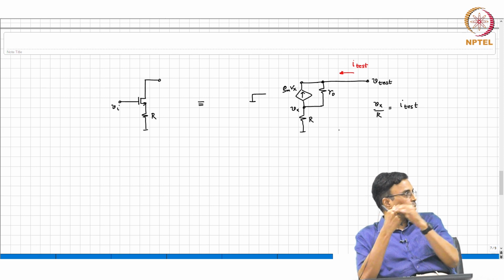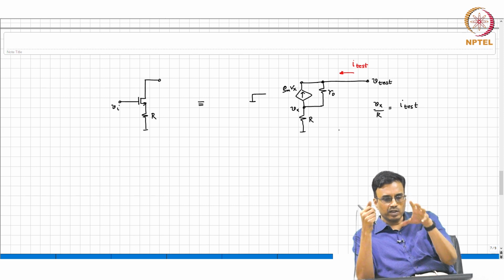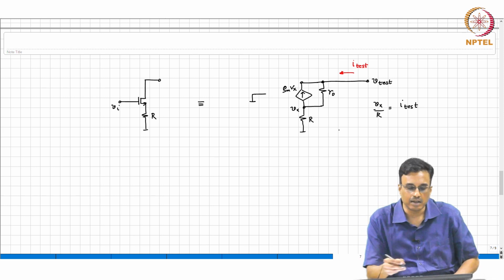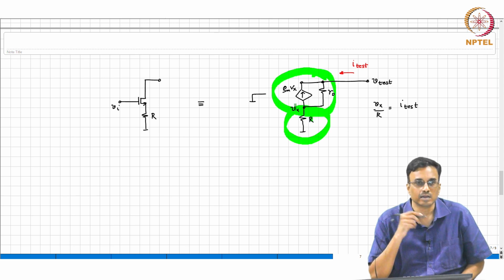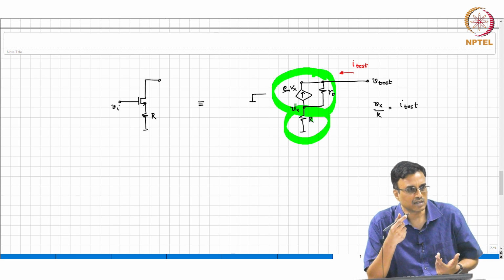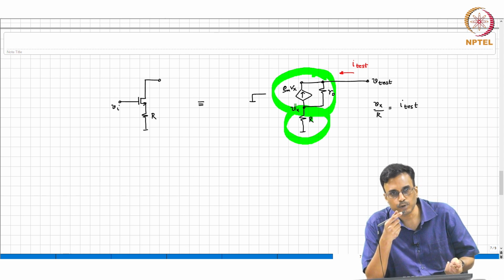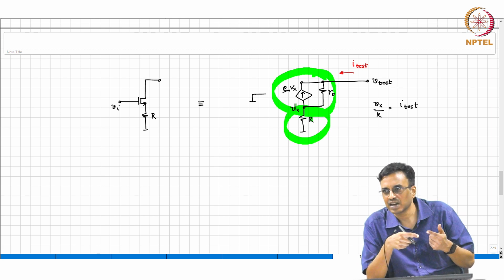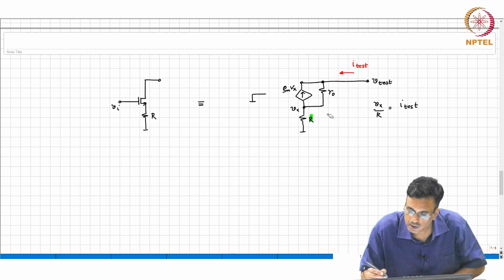And this particular case happens to be one such case. What do we notice here? A whole bunch of resistors are in series, correct? This character here is in series with R, right? So do you think it is easier to apply a voltage and measure the current, or push a current and measure the voltage? When things are in series, it makes a lot more sense to push current.